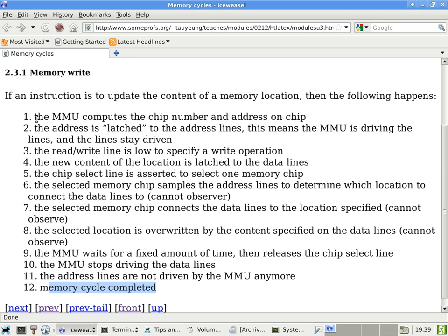And that's why DDR2 and DDR3 are fast, because you don't have to go through all these steps. The processor and the memory chip can have an agreement and say, I'm starting to read at this location, give me that location and also the next 16 or 8 or whatever number of locations. And from that step on, it is all based on synchronous operation. In other words, I'm assuming you can give me a new location every 2 seconds, so I will sample the data bus every 2 seconds. If there are any mismatches, then I'm in big trouble.